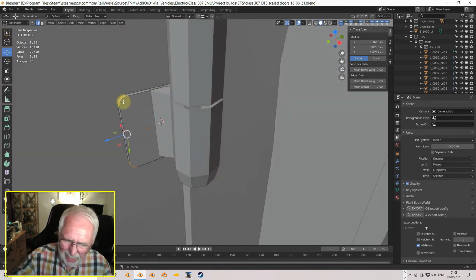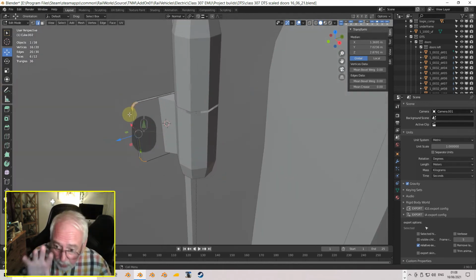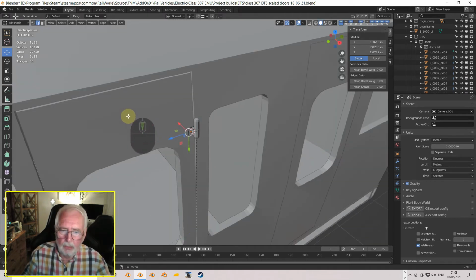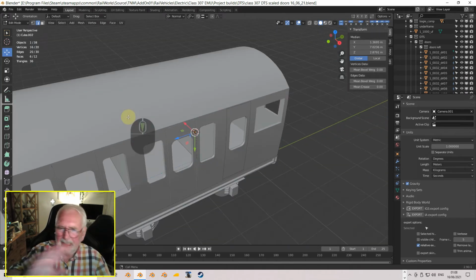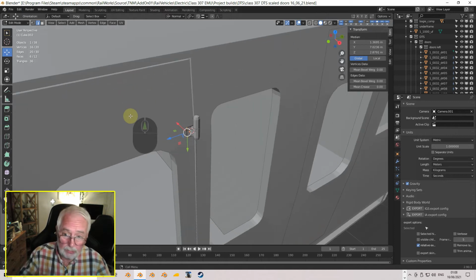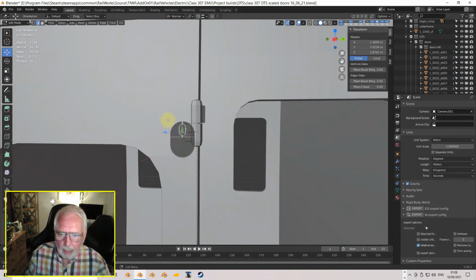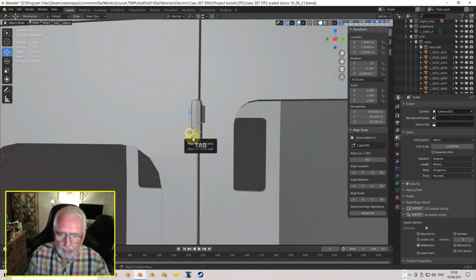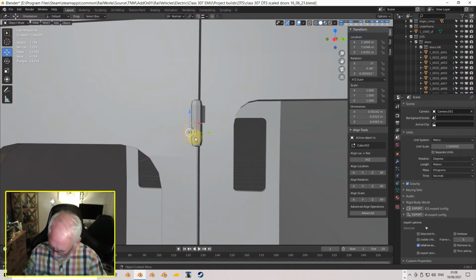So we've got a bit of shape to that for if you're going really close into it, but as we move out we don't need that detail and we'll lose that. Okay, so that's that one. Let's just duplicate it. So let's just copy it. Okay, rotate it 180 degrees in the X direction. Okay, let's flip it upside down.